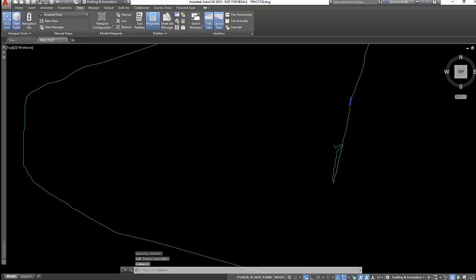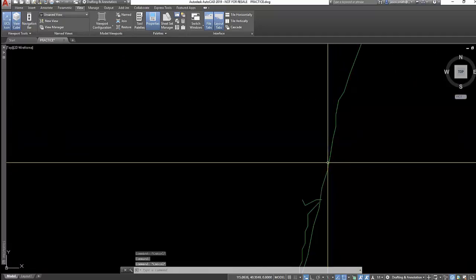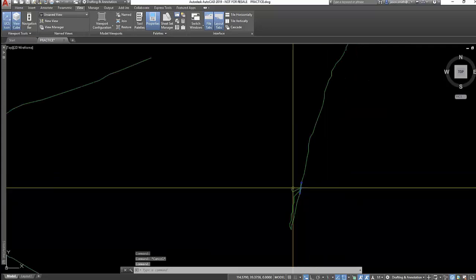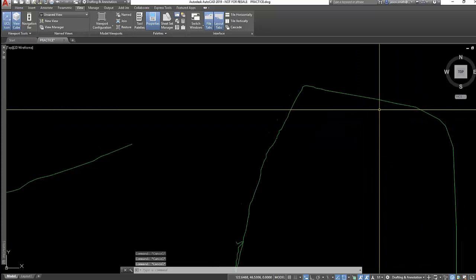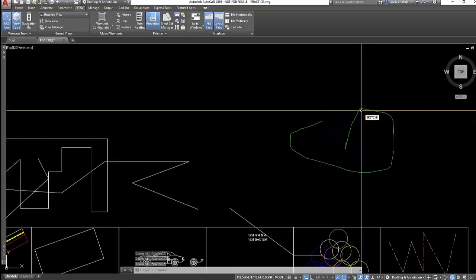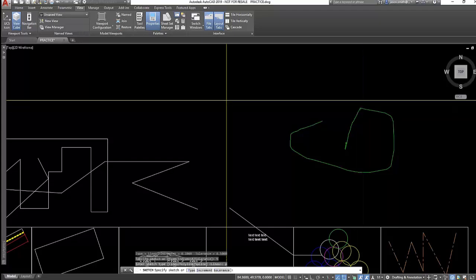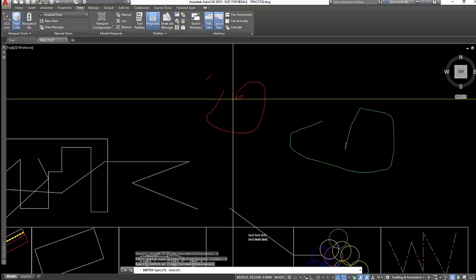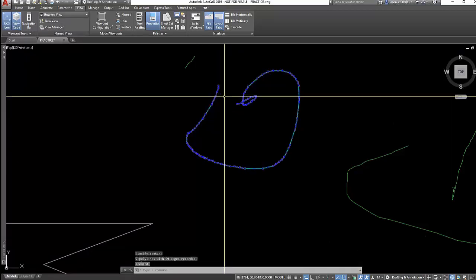Once completed, the line is actually individual increments of line work that you can then join together using any of the polyline edit tools. And the type option also allows you to choose a polyline or a spline option instead of lines, which will join it together into a single line.